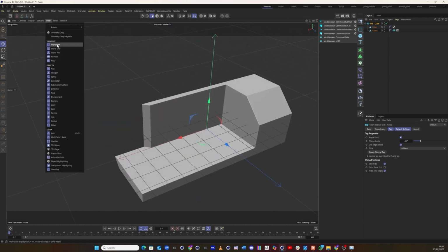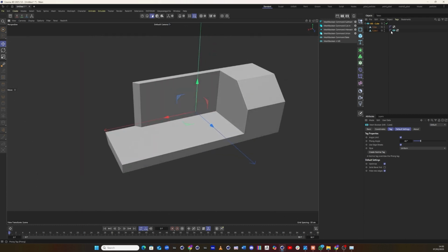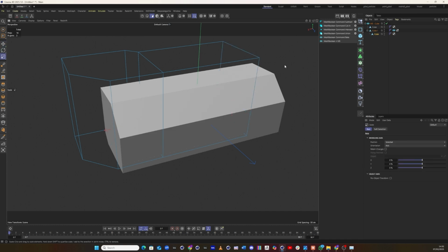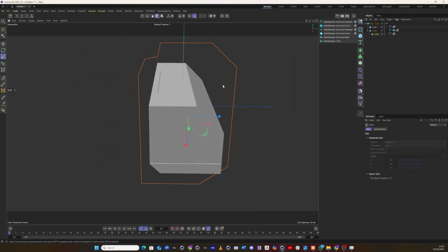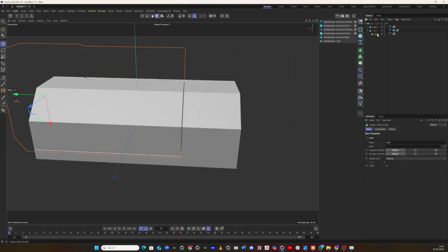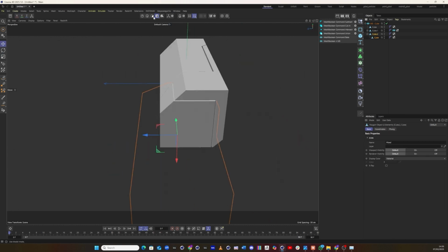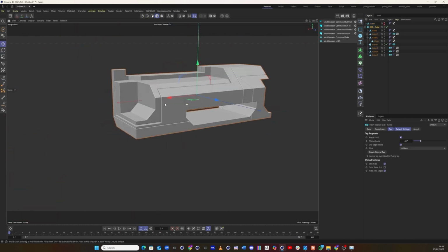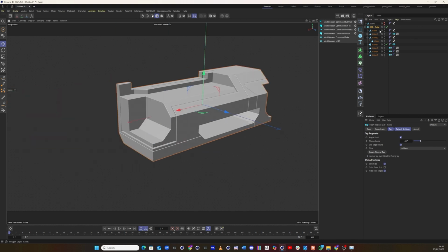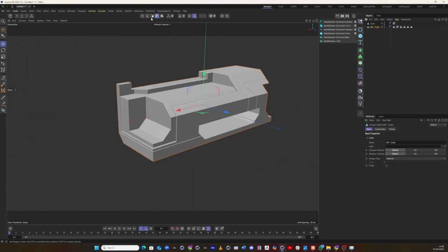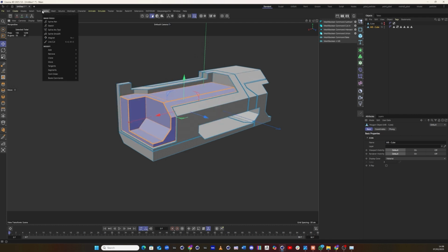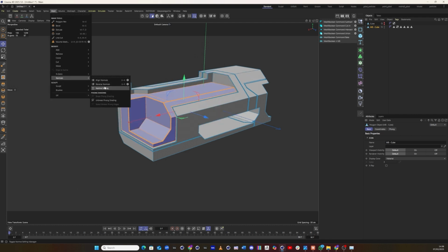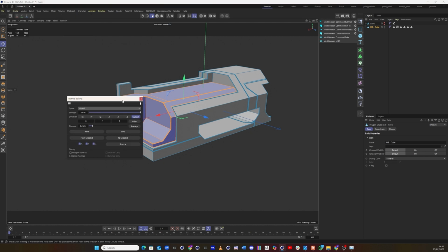Using the plugin, I start sculpting and shaping it. Let me fast forward through this process to show you the final result. As you can see, this is the object we ended up with. The object is subdivided using the Mesh Boolean plugin. However, there's an important quality control step you need to perform. Select and inspect each individual element to check for reversed normals. If you find any reversed normals, you should fix them to ensure proper rendering and intersection.